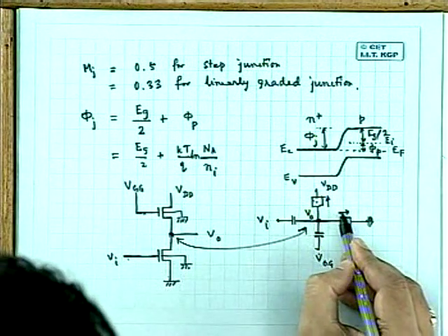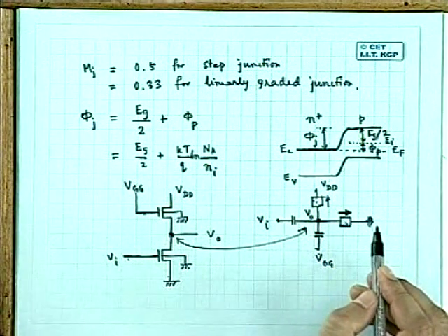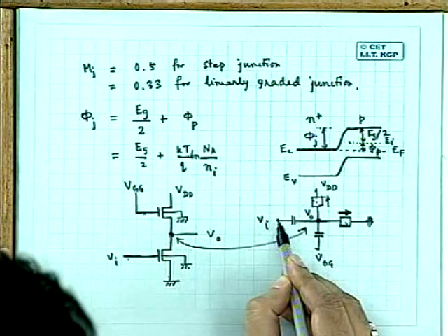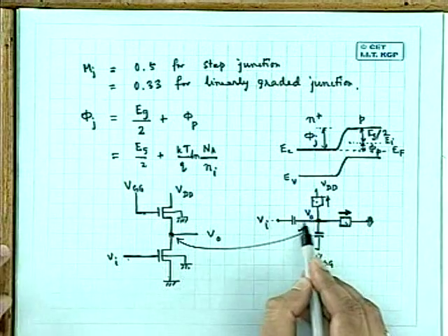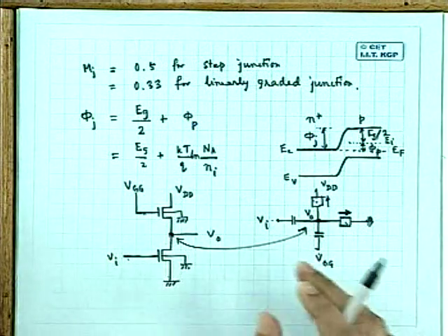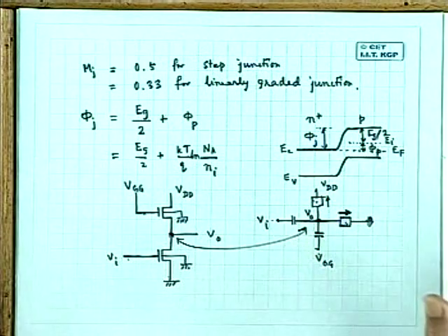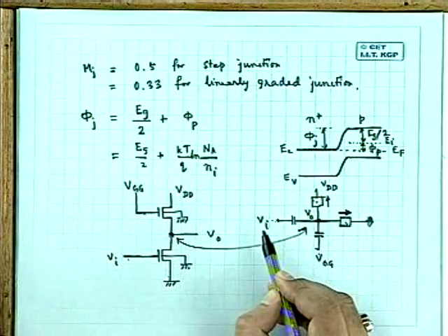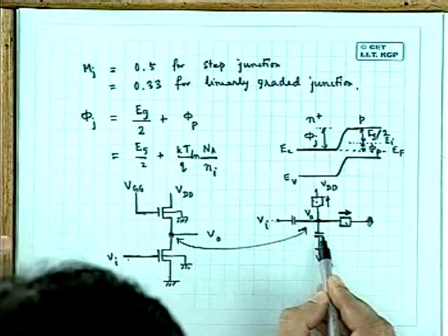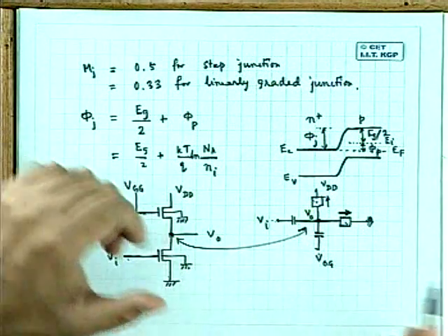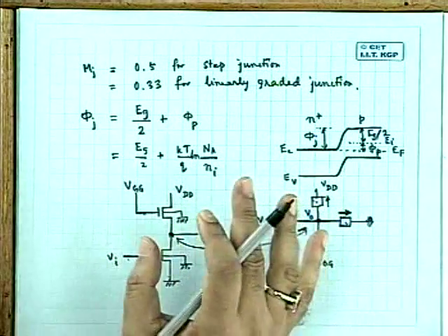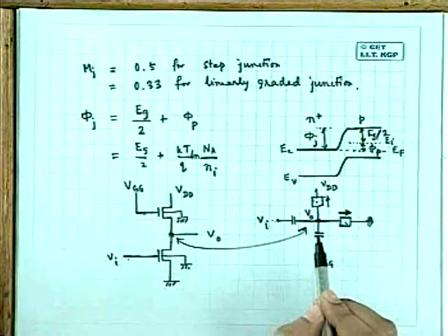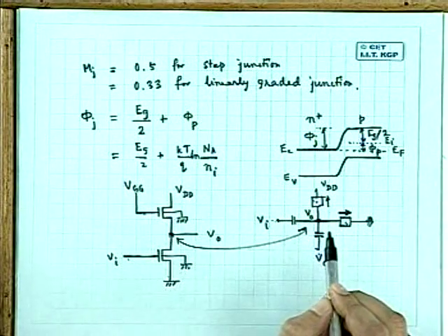So these two currents are straightforwardly obtained from there. And this current is nothing but C dV/dt: the capacitance of these two capacitors, which are CGD, CGS, etc., whatever the inter-electrode capacitances may be, multiplied by the rate of change of the voltage between the adjacent nodes.